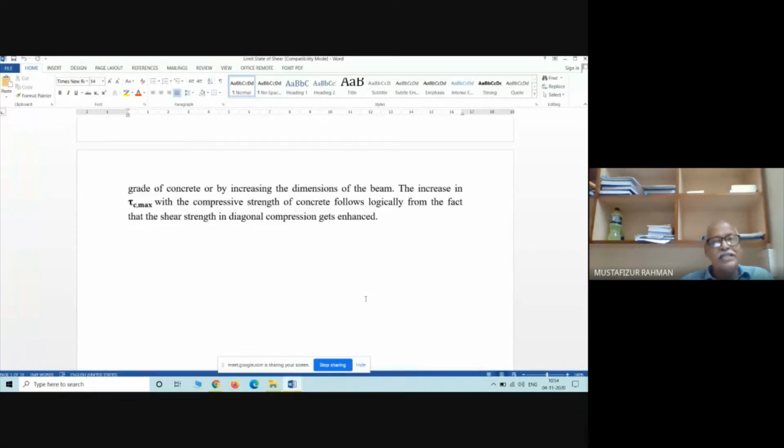So to resist this shear, we can raise the reinforcement available at the bottom to the upper surface. This will be able to resist the shear. So these are called bent up bars. In the links, the longitudinal reinforcement we have provided will be tied up with the help of rings.